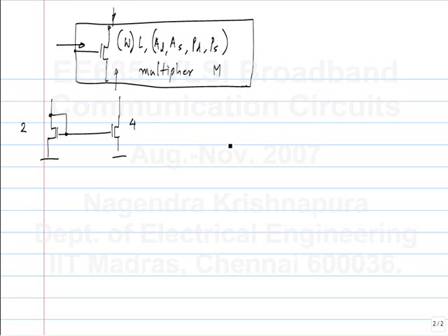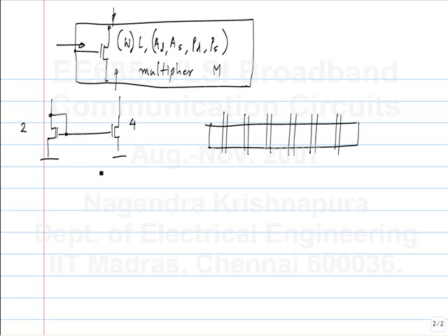So what you do is you have 6 stripes of the gate. Okay. These are the gate stripes and this is the diffusion. And in a current mirror, the source is common to the 2 transistors. The sources of the 2 transistors are connected together. So for instance, the common source I call S, and this I will call D1, and this is D2.